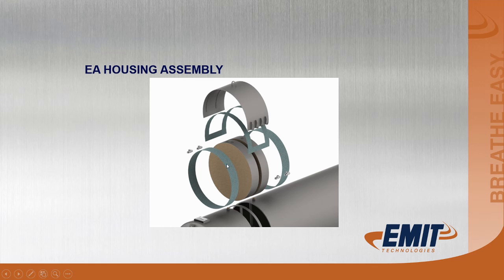Okay, the assembly of it is you've got your catalyst elements that go in the slot. There's a gasket material called Tetraglass, comes in a roll, and it's got an adhesive back on it. You just stick it to the catalyst element and drop it in the spot. And this gasket material right here, also 1.5 inches wide, just comes in a roll, and you cut it to length and you stick it inside the door and on the contact surfaces where you want your seal.